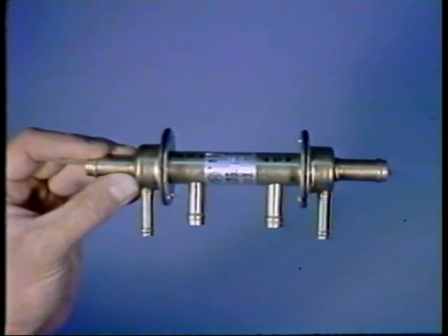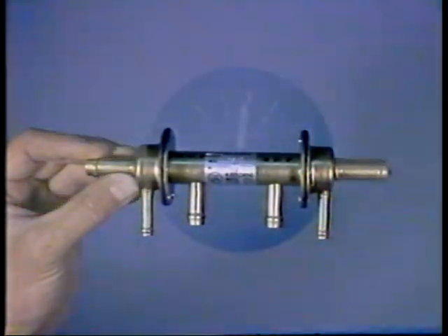Twin-engine aircraft use a central manifold and check valve assembly, through which both pumps are connected to the gyros. In the event of an air source failure, one of the check valves will isolate the inoperative part of the system, allowing the remaining pump to carry the load. A source indicator in the aircraft panel gauge will show a red button to indicate which source is out.